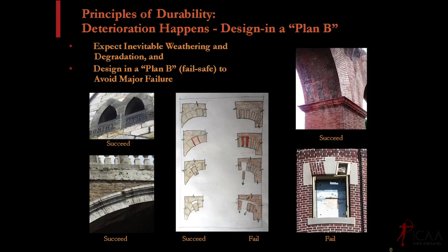And I think it shows the beauty of using a wedge-shaped brick, or in a lot of the Roman construction where they often use a wedge-shaped brick, and where they didn't, what they typically did was the mortar joint goes to basically zero at that inner edge. And I'm diagramming that here with the wedge shape, where you lose this mortar, the wedge shape drops, and it pinches in and locks into a new position of stability, and you don't have a collapse or a loss of stone, and you don't have a progressive collapse.